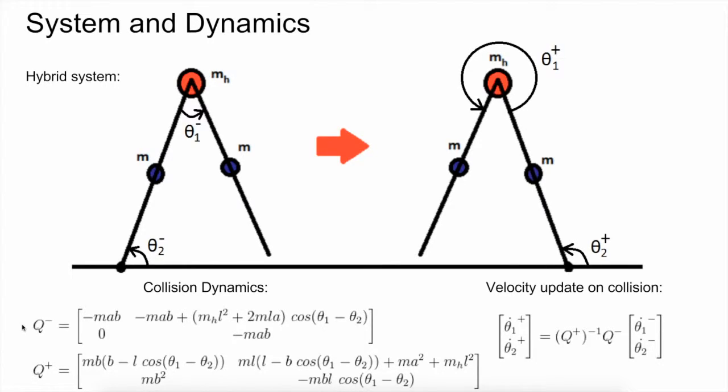In order to model this physical phenomenon, we calculate two matrices which symbolize the angular momentum before the collision and the angular momentum after the collision, and we equate them. It's critical that when we're doing these calculations, we choose a joint which is unactuated. For example, the momentum is conserved about the previous stance foot and about the new stance foot, but is not conserved about the hip, which is actuated. It's critical because the conservation of momentum is directly caused by the net zero external torque. The matrices that we use for the compass gait inelastic collision with the ground are shown here.